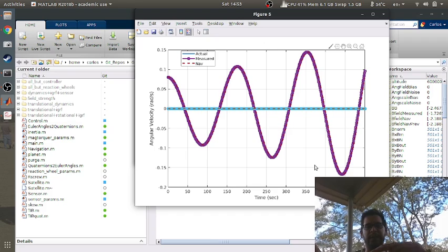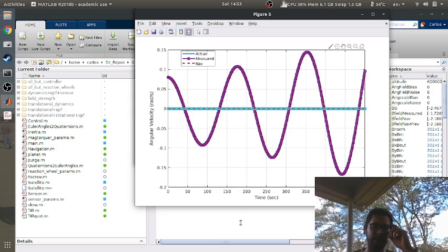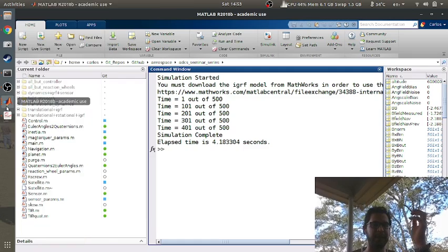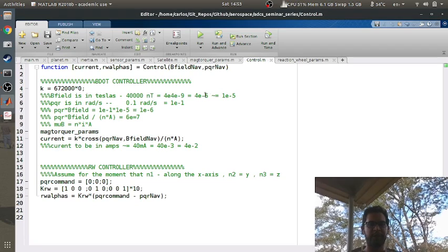So again, I'm applying proportional control to a type 2 system, or really derivative control to a type 2 system. It's kind of weird. And so what I need to do is add in, unfortunately, the star tracker measurement. And so I can add in the noise again. I mean, that's not really a big deal. I was hoping I didn't have to do this, but unfortunately it looks like my hands are tied.